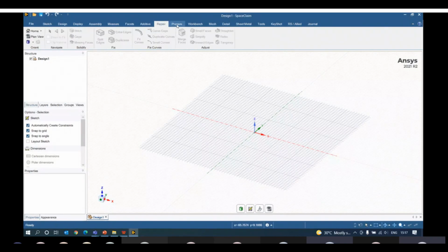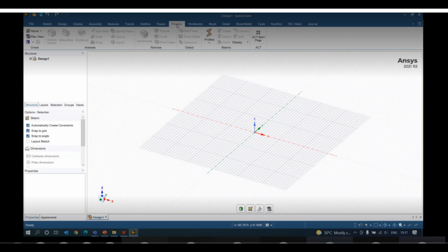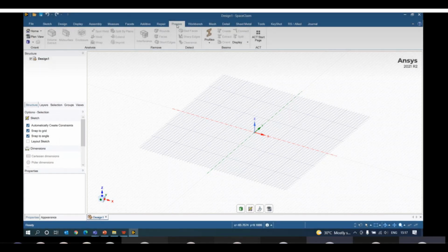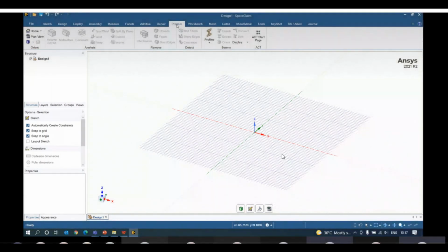The most important thing that we consider in terms of working on a simulation is where you design geometry on different platforms. That could be any CAD tool, you can say, SolidWorks, Creo, CATIA, anything. But when you are trying to import it for simulation, there is a GUI change, with which you get to see a lot of differences in your geometry, and it will not give you a proper geometry.